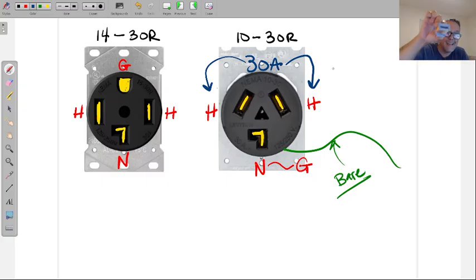But this coil is not a load. There's no load capacity here. It's just being magnetized, so there's no amperage being produced by it. Well, there is, because we can never say there is no amperage. If there's resistance and voltage, there's amperage, but it is below 1 amp, so for us that means 0. If you were in physics, you would get down to the micro world and give me a number like 0.0001, but for us, I can't measure that, so it's nothing.